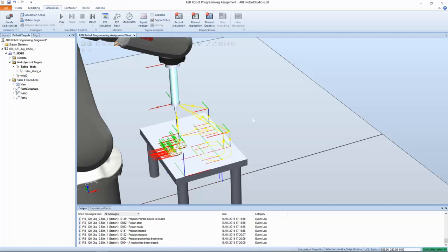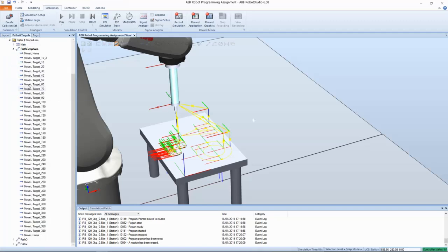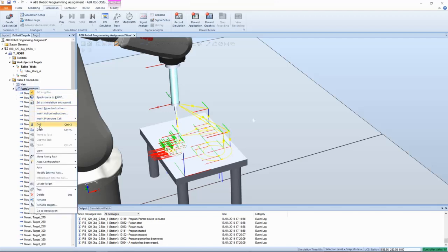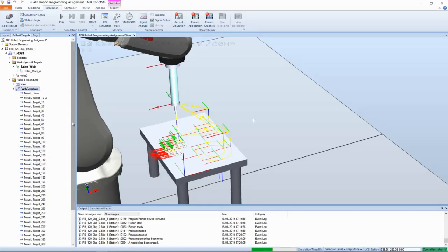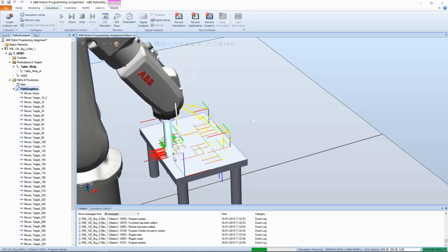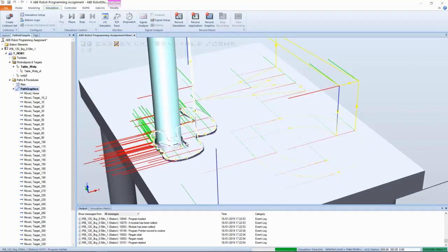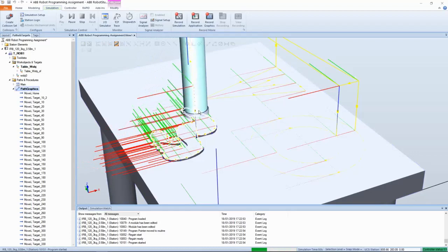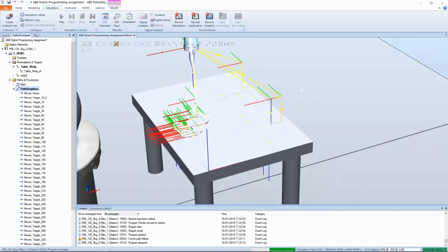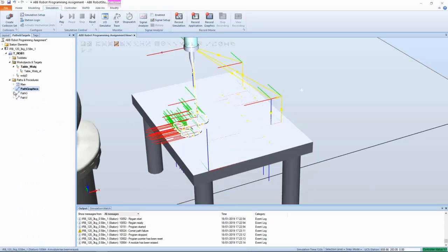We can have a look at the paths, each one separately, by going into the paths and procedures and paths and graphs. Let's run those. You can see calculate, and it goes. Please note that the tip is defined so that it suits the real life condition. In this case, the tip model is bigger than the actual tip in real life, therefore the tip endpoint had to be modified to suit that curve.